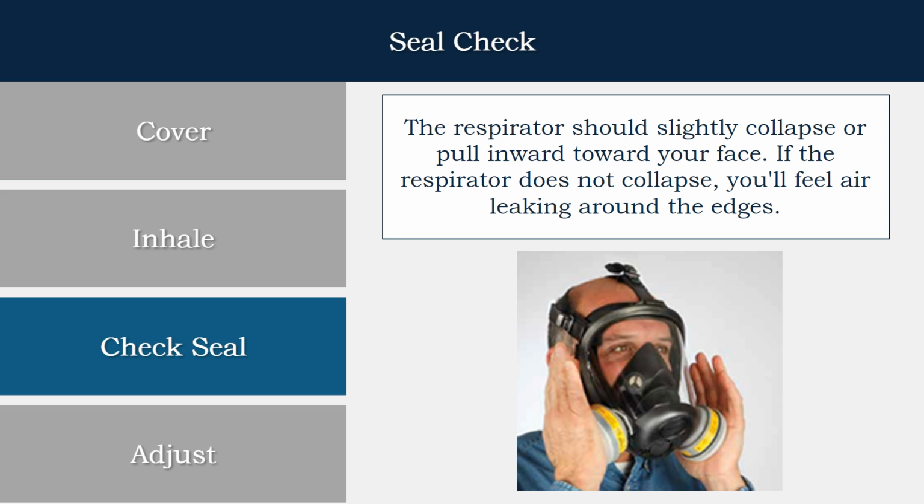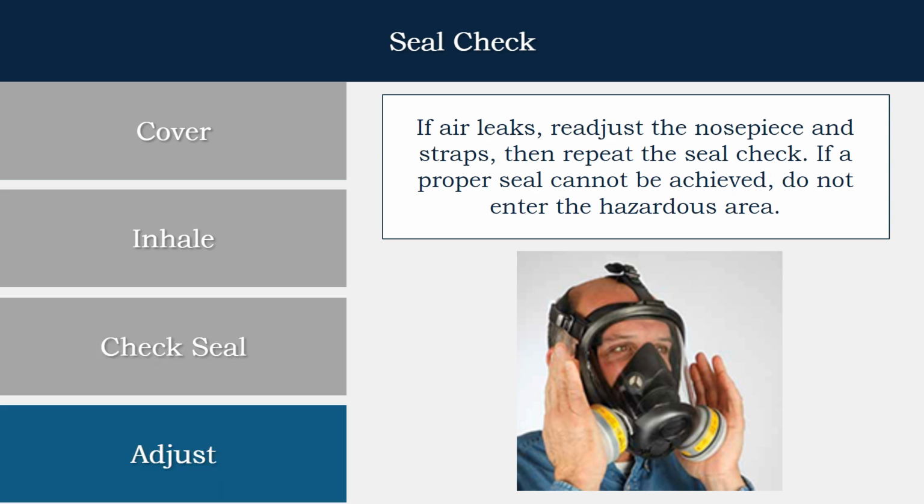If the respirator does not collapse, you'll feel air leaking around the edges. And 4. Adjust. If air leaks, readjust the nosepiece and straps, then repeat the seal check. If a proper seal cannot be achieved, do not enter the hazardous area.